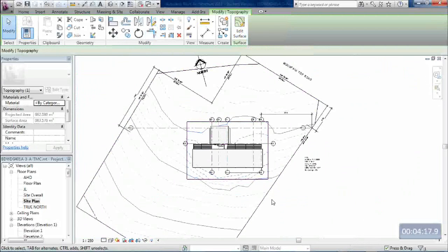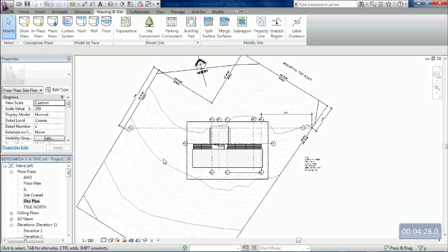Okay, now the next step is, and I've already done this, had it prepared for you, but I'll show you what I've done. In the meantime, you probably won't have this set up like this at the moment. You can see that I've got a primary contour and a primary contour, and in between those primary contours I've got secondary dashed line contours every 250 millimetres. But there's something going on inside here. There's actually too many secondary contours, and I'll show you what I've done to create that.